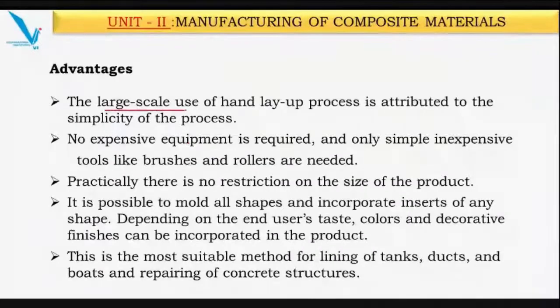The large scale use of the hand-layup process is attributed to its simplicity. It is very simple and does not require any advanced technique. What you require is a one-sided mold, a brush, some pots to mix the resin, and a roller. These are things you can easily purchase from hardware shops, and you can start. At the student level, students generally do use this technique for projects. For research purposes, definitely this can be used. No expensive equipment is required.